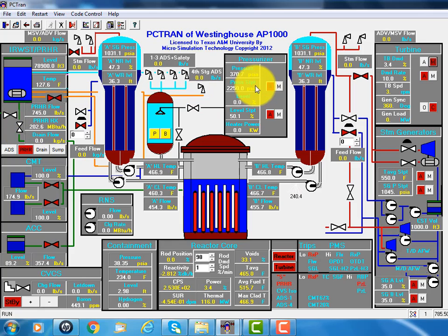Only when the pressure of the reactor becomes the same as the containment pressure. So just by gravity, this drain valve will open to replace the coolant loss. So this new concept cools the core to remove the decay heat.